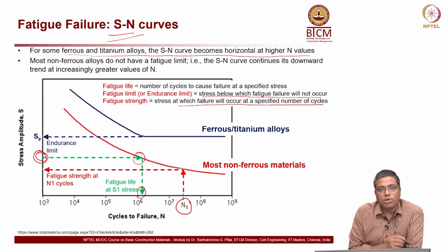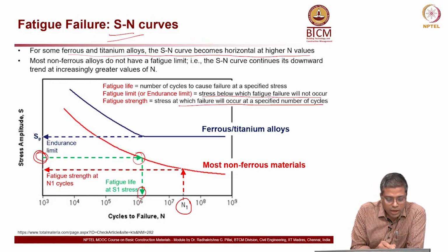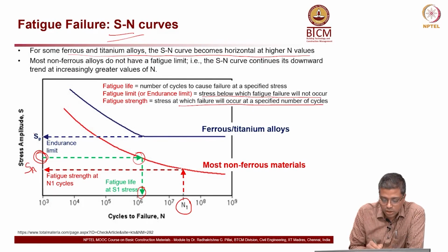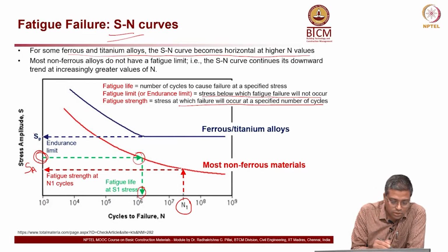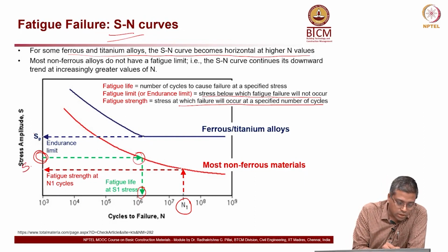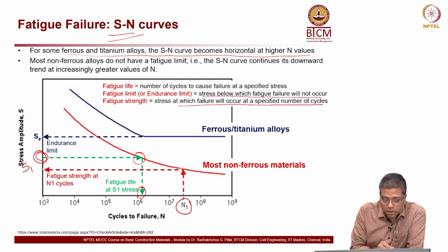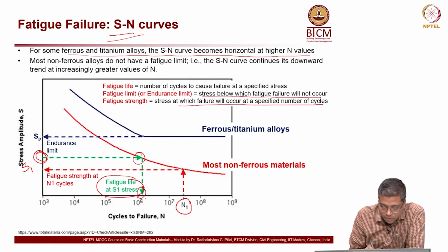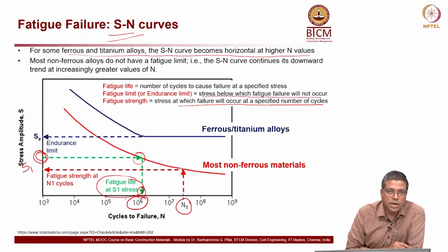That is about 10 to the power of 6 cycles. Now, if this is the stress which is applied, S1, so that there is no confusion, it comes here, the green text here, it is saying fatigue life at S1 stress. So, that fatigue life is 10 to the power of 6 or about that.